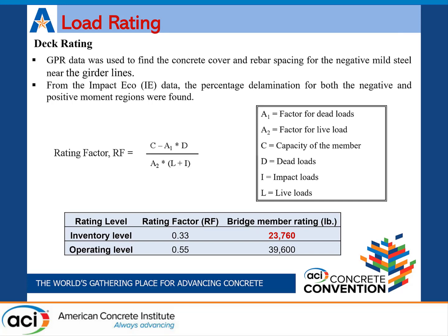So we incorporated GPR data and impact echo data to find out the capacity of the deck. After doing the load rating, we found that the bridge rating was 23,000 pounds at inventory level, and at operating level it was around 39,000 pounds. In this case, the rating factor is less than 1, so we need to post load on the bridge, or we need to go for urgent retrofitting options.